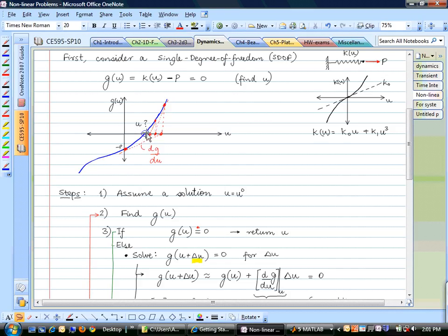When people use a tolerance as small as 10 to the power minus 6, it takes only 5 or 6 iterations to get down to that level of tolerance. That's the consistent Newton-Raphson method. There are other methods, modified Newton methods, which do not display the second order accuracy. So essentially this is what is going on in nonlinear solution methods.